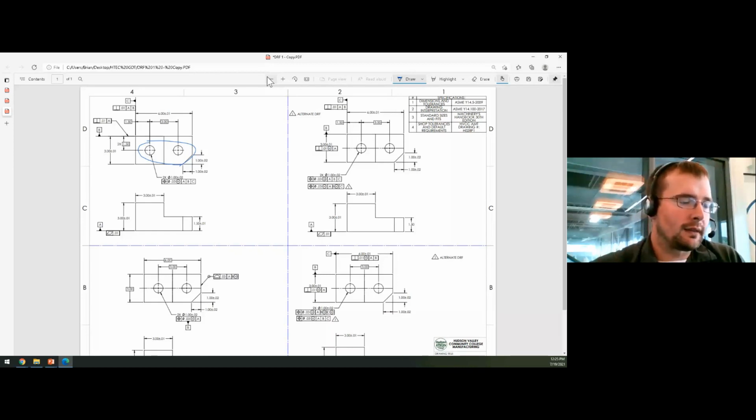I try to relate things to, if you're squaring the head in the milling machine, this controls your orientation. You indicate the vise, that would be like your 2 points of contact in datum B, that'd be your clocking, and then your orientation. And then you have 1 point of contact, which would be like a stop on the x-axis of the machine. And of course, the y-axis would be the solid jaw, and the z-axis constraint would be the z on the machine, or whatever plane the spindle is perpendicular to. That explanation, or a similar one, has really helped us.